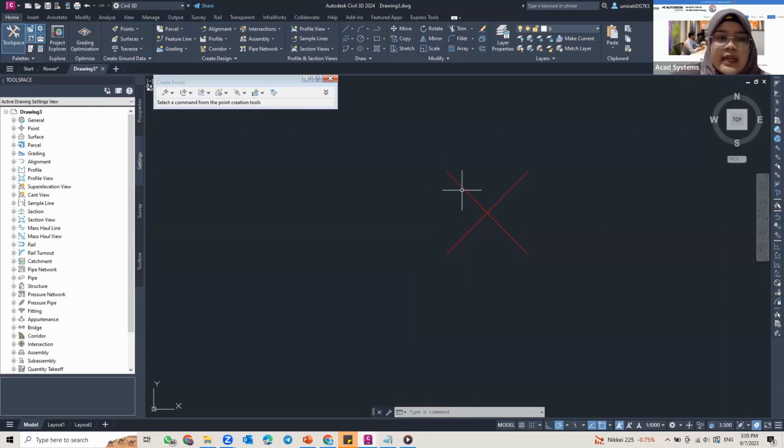And then how do you create the point marker using your own specification? Let's say I'm going to add some description keys, for example, EG, and then I have the specific point marker for the EG, for example, square, circle, and then whenever I add it, it will show the exact point style.